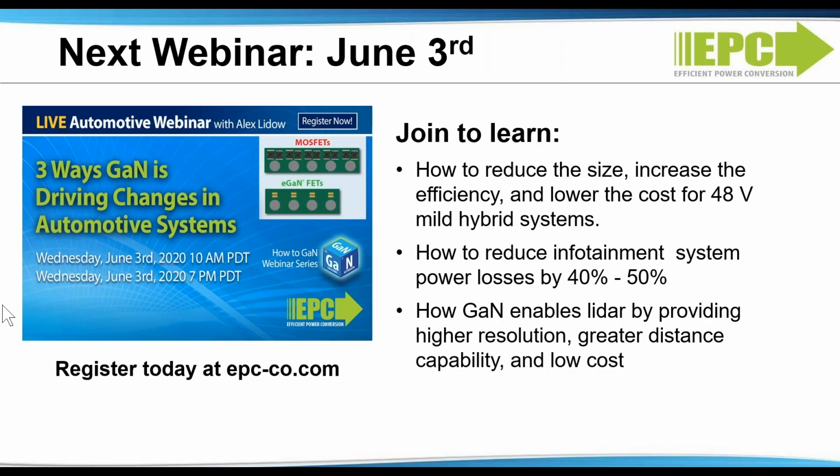LLC converters are soft switch, so where does the value of GaN come from? GaN devices have much lower output capacitance or COSS compared to MOSFETs with the same on resistance and voltage rating, and that means lower energy for ZVS, zero voltage switching transitions, and this results in lower ripple in the transformer. So that means you have a higher effective duty cycle. Also, you have much lower input capacitance, and therefore much lower gate drive power consumption.